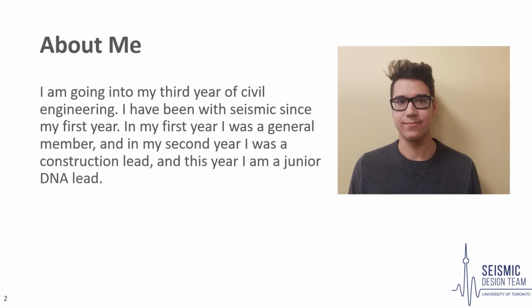I hope this session will help you further your understanding of the concept of torsion, which is important when considering how members behave along a tower, specifically when looking at torsion that's caused as a result of the weighted rods that are added to the tower. If torsion is not properly accounted for, the tower may experience failure in shear as a result of torsion.